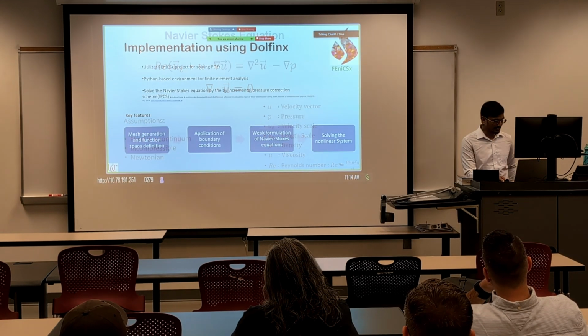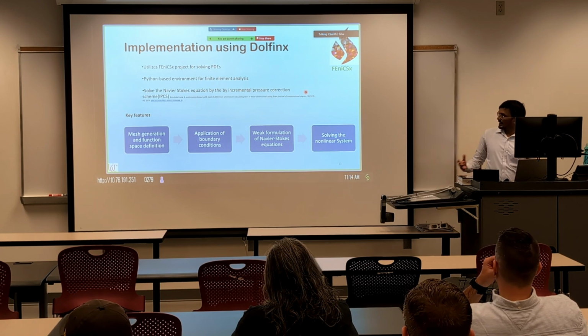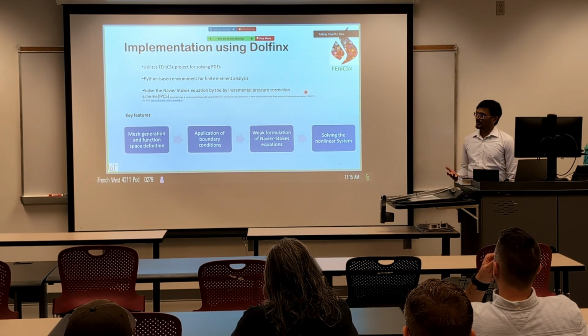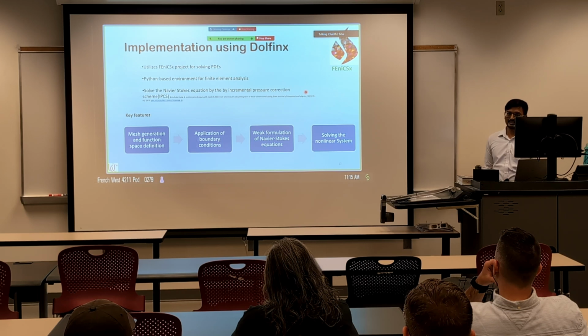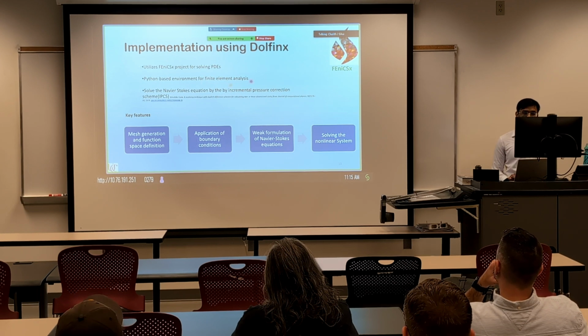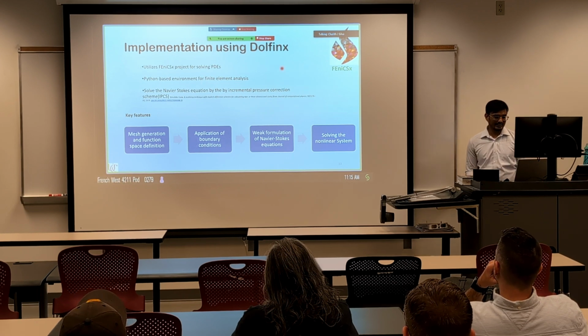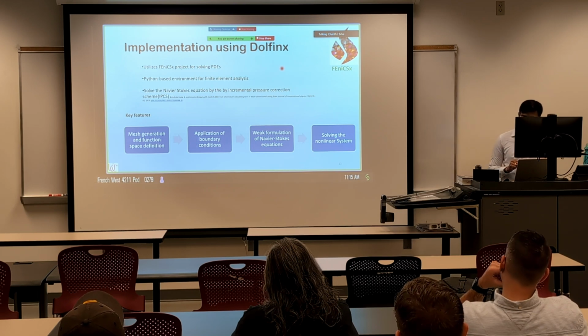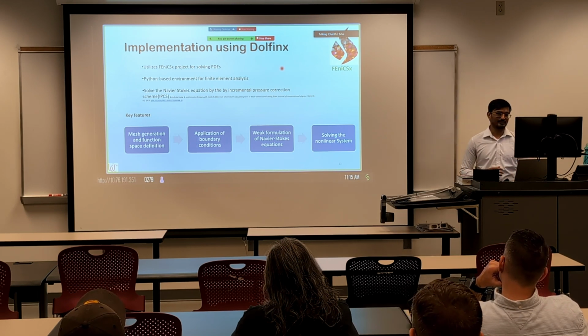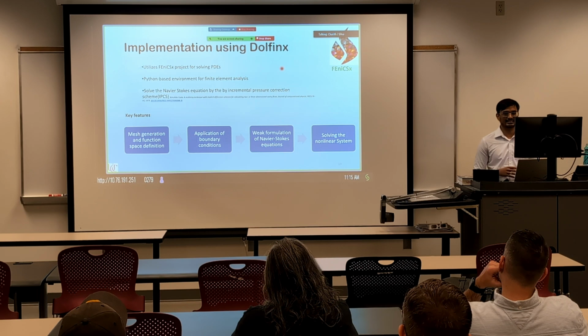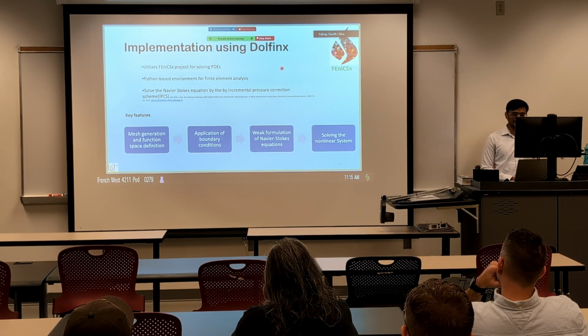And in my case, I have used a special Python module called DolphinX that is created by the FEniCS project. And it is a Python-based environment for finite element analysis. There, the DolphinX module uses a special technique called incremental pressure correction scheme to efficiently solve the Navier-Stokes equation.